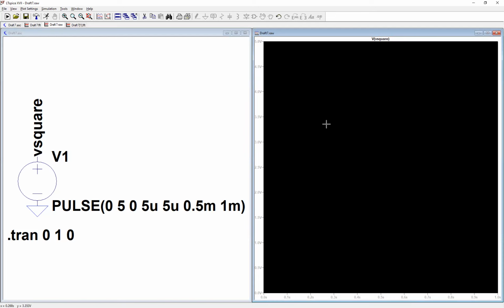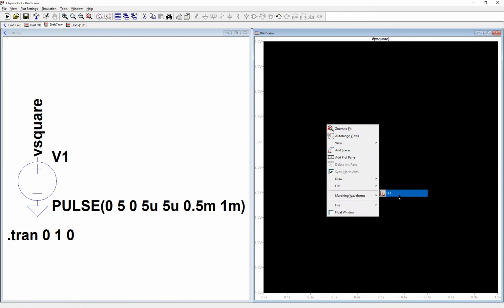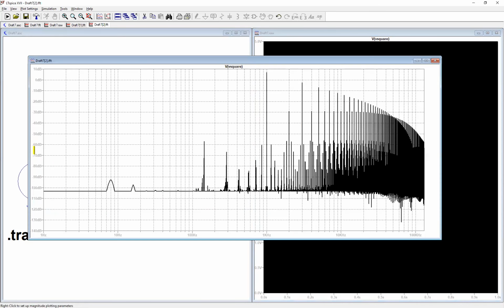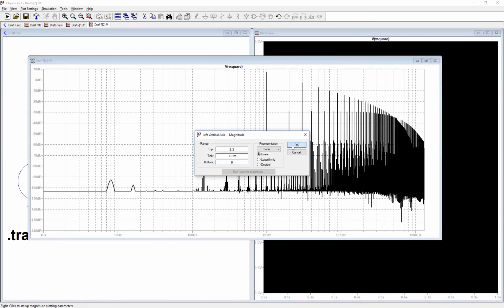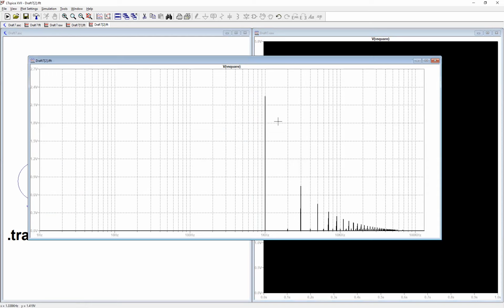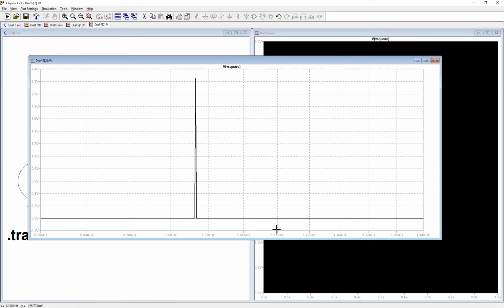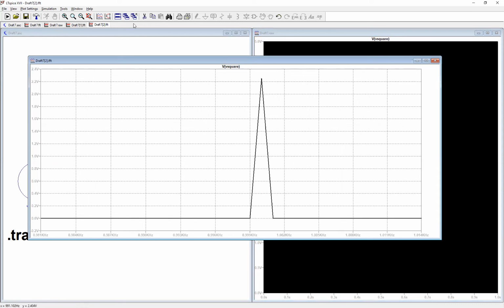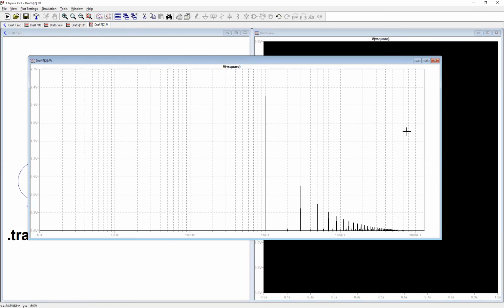So now I'm going to extract the FFT of this signal, and linear. You can see that now the harmonics look more like lines, as I was expecting. A harmonic has to be like a line, you see. If I zoom in, of course, it looks like there is still a little triangular shape, because again, this signal I'm plotting is not an ideal periodic square wave. But this one looks more like something I would expect from the spectrum of a square wave.